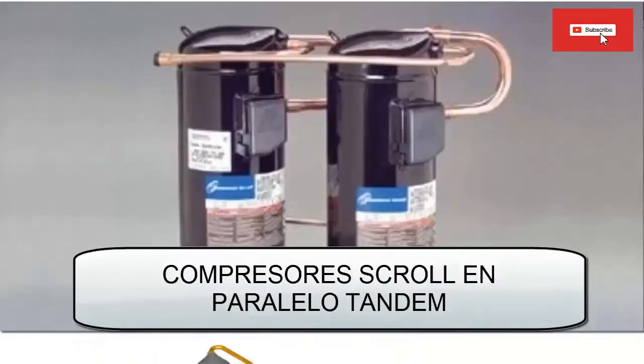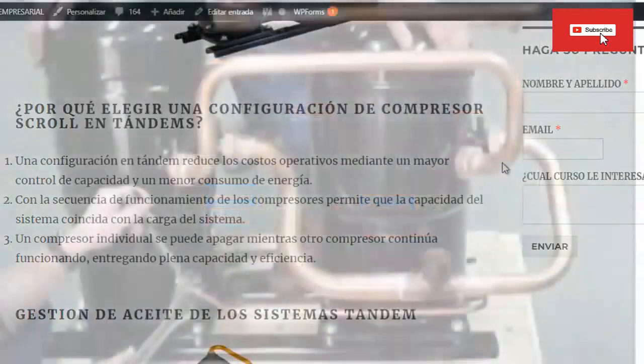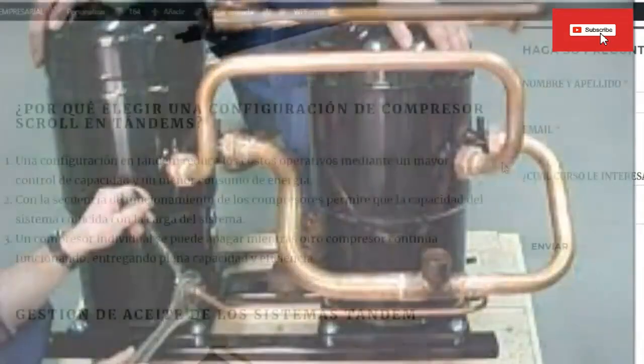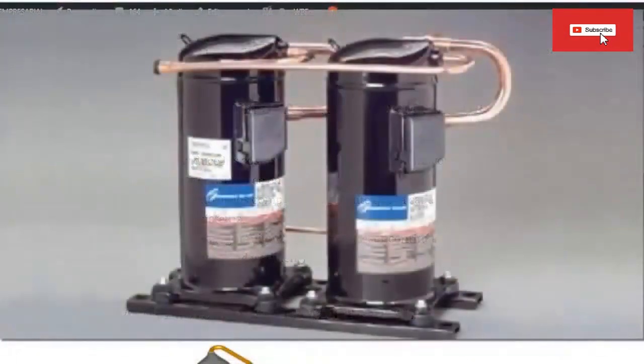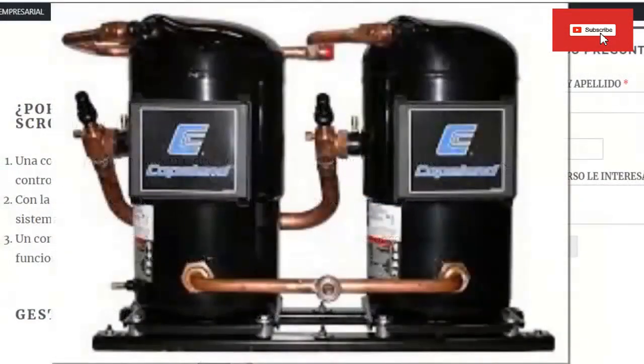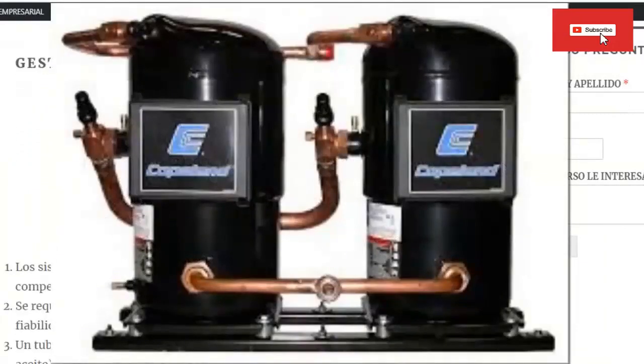Why choose a tandem quad compressor configuration? 1. A tandem configuration reduces operating costs through greater capacity control and lower power consumption. 2. The sequence of operation of the compressors allows the system capacity to be matched to the system load. 3. An individual compressor can be shut down while another compressor continues to run, delivering full capacity and efficiency.